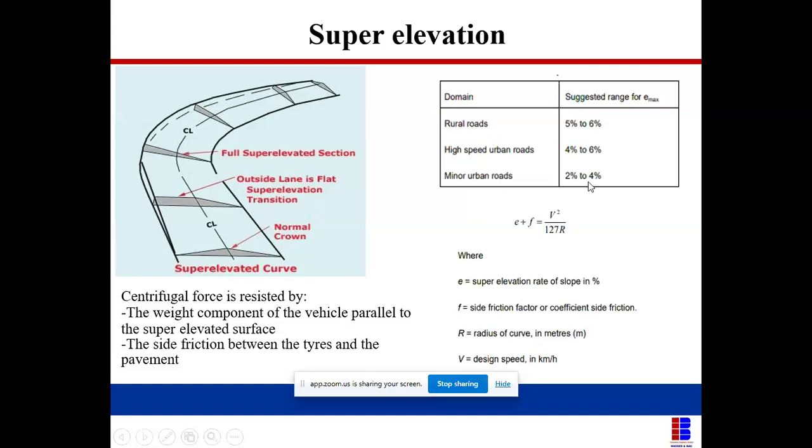So these are the first criteria you input when you are in your design. You input design speed first, then the next one is the elevation. Put in this maximum elevation. After that, the software will calculate the curves automatically. Then you go and see where the curve has a shortfall based on the standard in the manual.